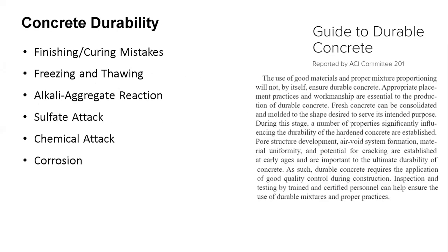And so durability is a function of a lot of things. And there's a lot of things that we think about, I should say, with durability. The quality of the finishing and the curing has a huge impact on it. The exposure to freezing and thawing is very important. The aggregates that we use can be very important. We don't want to create an alkali aggregate reaction, alkali silica reaction in concrete. And we have to consider things like sulfate attack and chemical attacks and corrosion of the rebar.